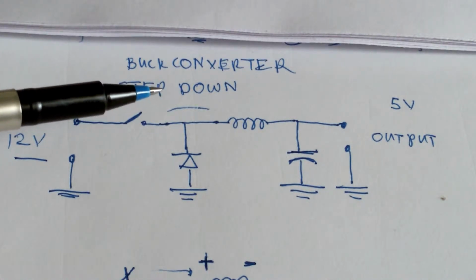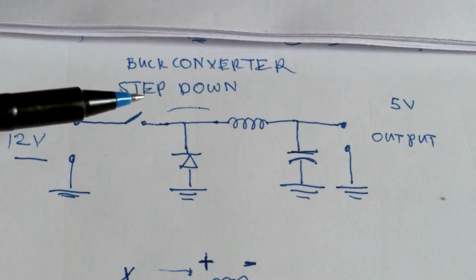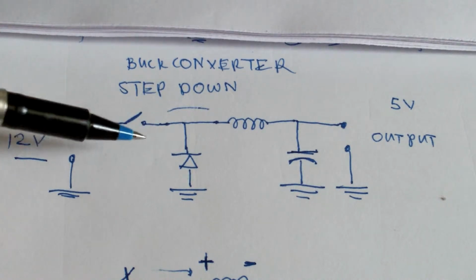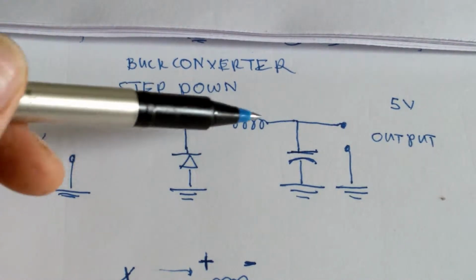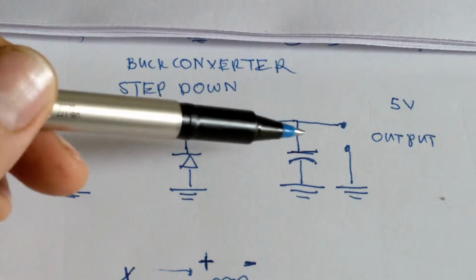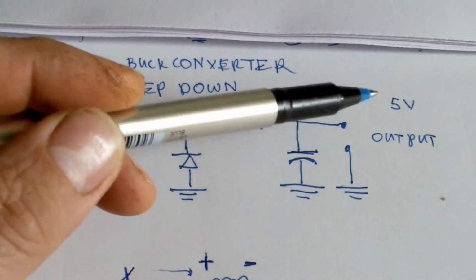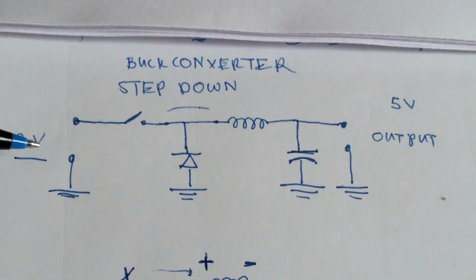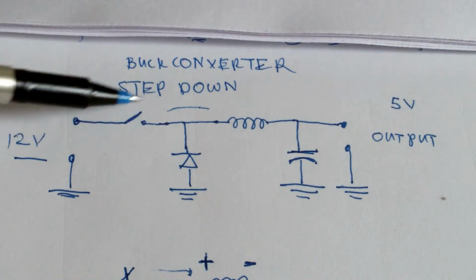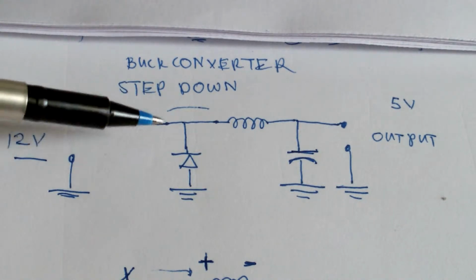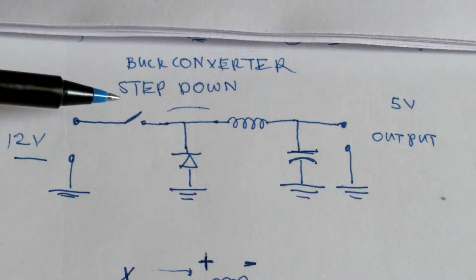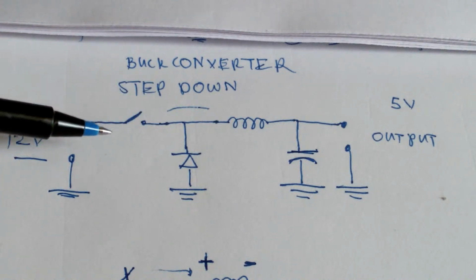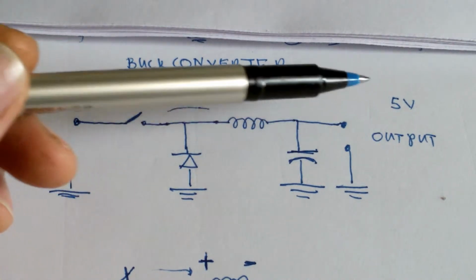So how does this buck converter circuit work? It works through a fast acting switch charging and discharging your inductor, and at the same time your inductor charges the capacitor, and in turn you will achieve a lesser voltage compared to your input voltage. This is a chip that you can purchase in the market today that has good regulation in order for you to have a steady output.